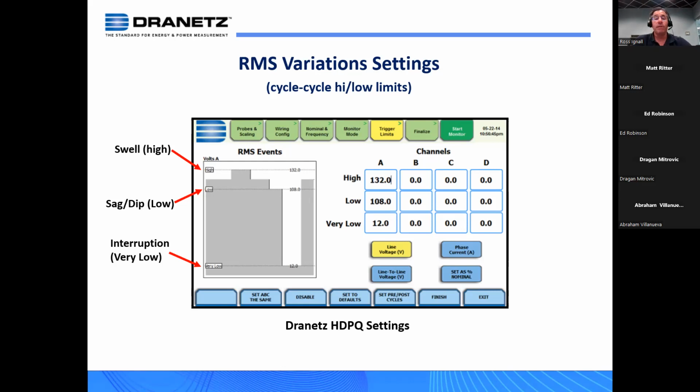very specific application. The reason being is that the current's always fluctuating, something small to something large, and as your power system goes through its dynamics, it's going to create a lot of triggers. So you need to know really what your loads are and what your application is. They work perfectly fine, but again, be careful what you wish for when it comes to that, because you may get a lot of triggers that you may not expect.